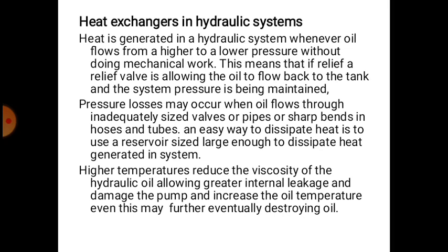Heat is generated in a hydraulic system whenever oil flows from a higher to a lower pressure without doing mechanical work. This means that if a relief valve is allowing the oil to flow back to the tank and system pressure is being maintained, heat is generated. Pressure losses may occur when oil flows through inadequately sized valves or pipes or sharp bends in hoses and tubes.